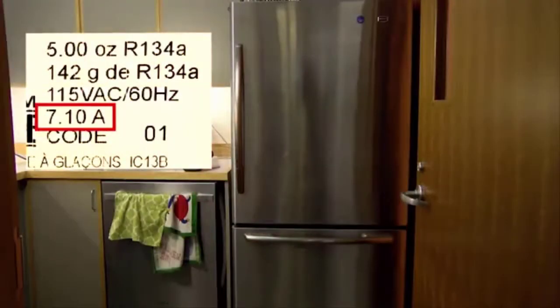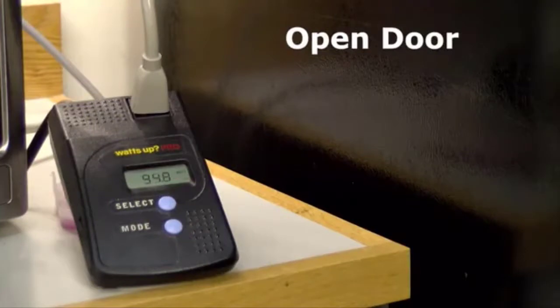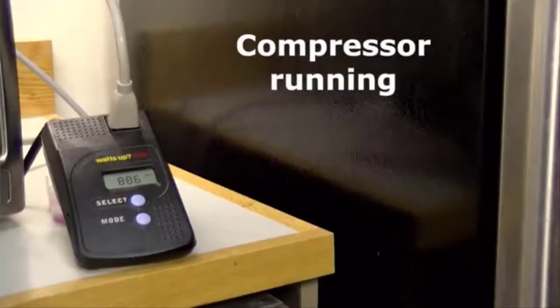Finally, a refrigerator is a bit more tricky because while there's an amperage rating on the refrigerator, it cycles on and off with the compressor, as well as when the light goes on and off with the door open. So it goes very low when the light is off, and then it goes slightly higher when the incandescent light bulb turns on and the door is open, to 94.5 watts. The power then goes much higher to 880 watts at the peak power with the compressor running.